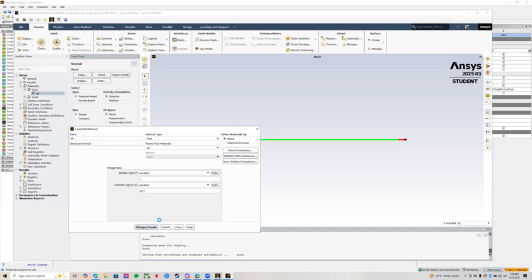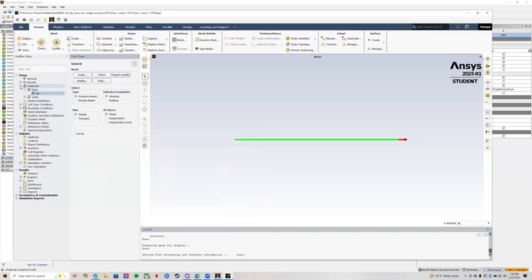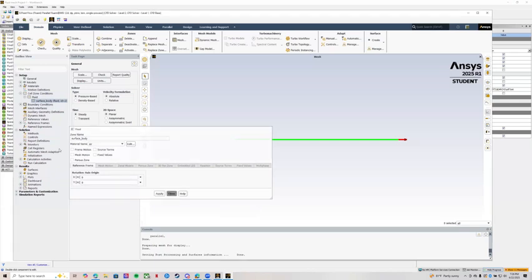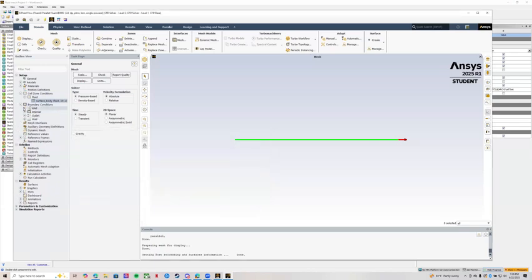So we're going to go ahead and change that real quick. So there we go. We're going to close out, close our fluids. Cell conditions, we can check. We're going to just check to make sure it's an air fluid again. It is, so we're all good. Boundary conditions, we're going to go to our inlet, and we're going to change that back to a velocity inlet.